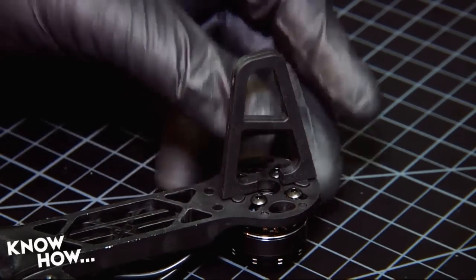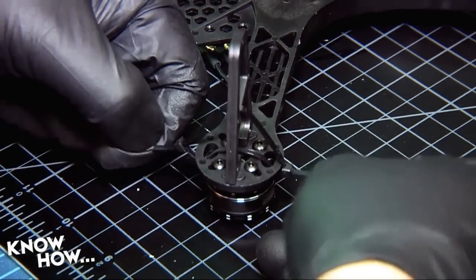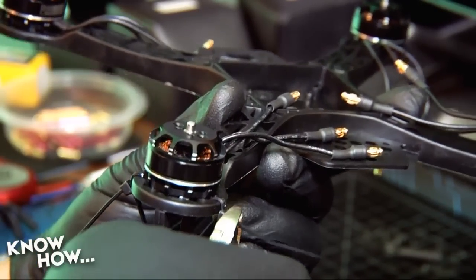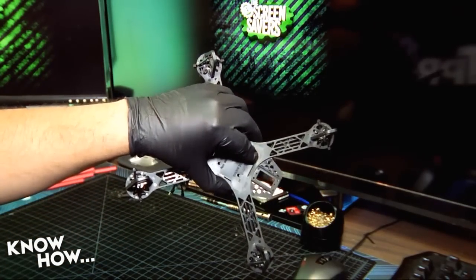With the motors mounted, attach the 4 landing feet to the bottom of each arm. You want them on now before we start wiring the motors and ESCs so you don't accidentally thread wires through a landing mount. Once in, use a pair of small zip ties to secure the landing gear onto the arms.